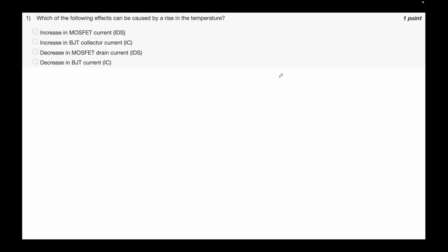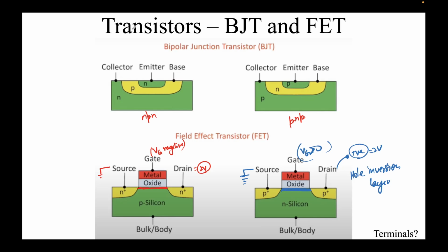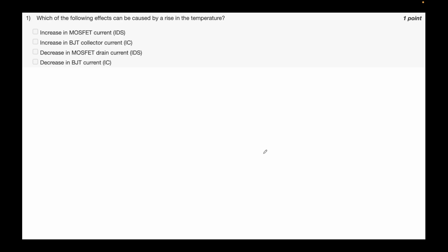I know I have not introduced the drain current concept, but I had given a hint that when you apply some drain bias, current can flow between source and drain, which was the case when we saw the emitter base, right? You forward bias the emitter base and reverse bias the base collector junction, and you will have your BJT in forward active. So we'll talk about FETs in a bit more detail later.